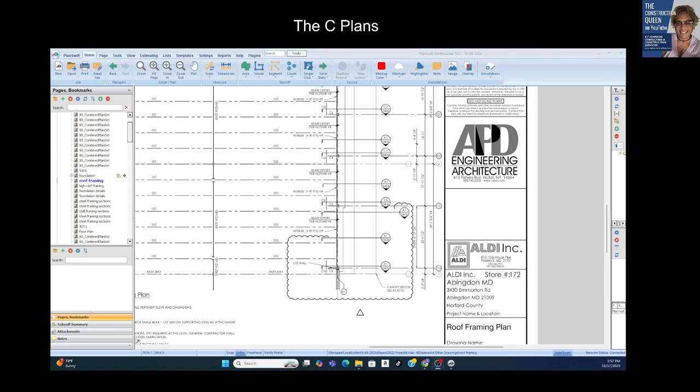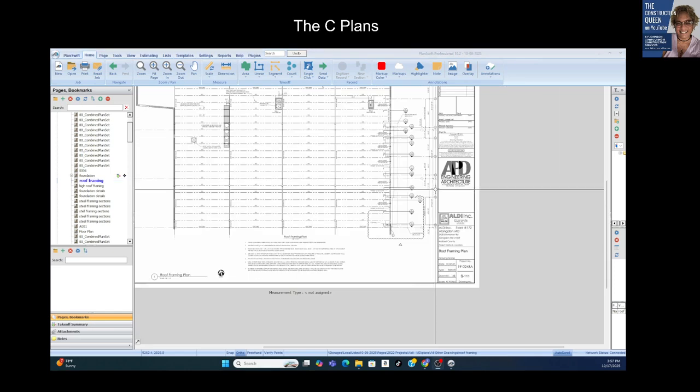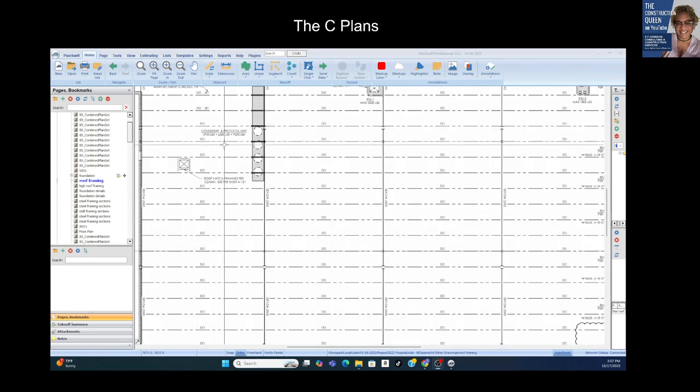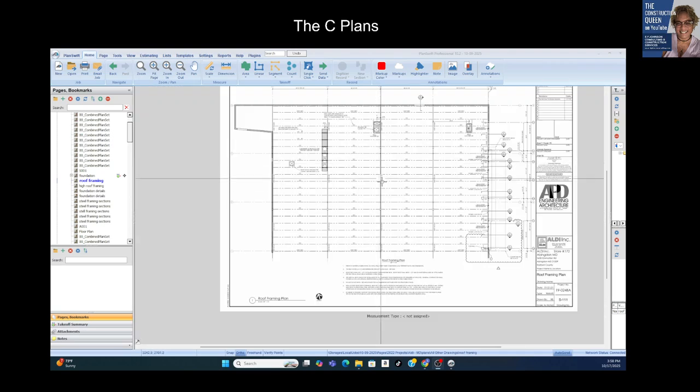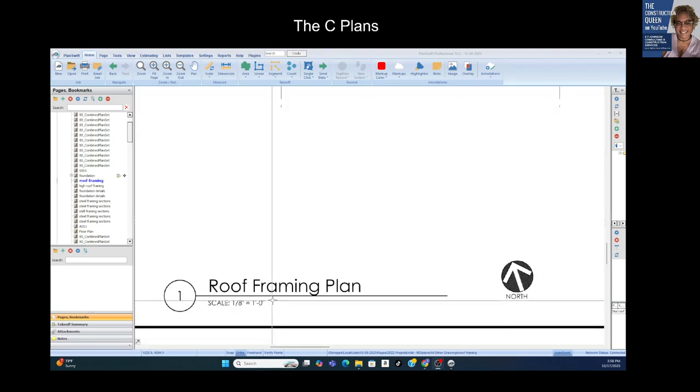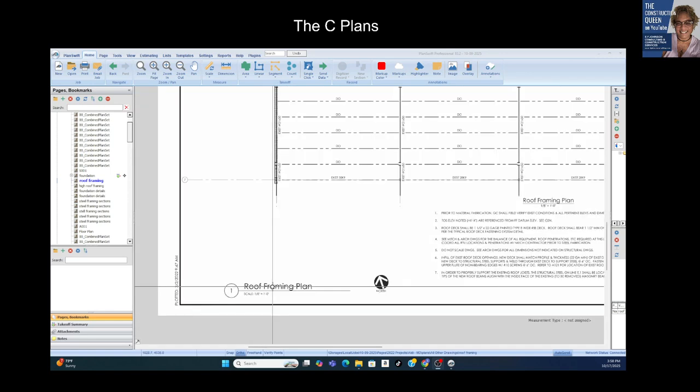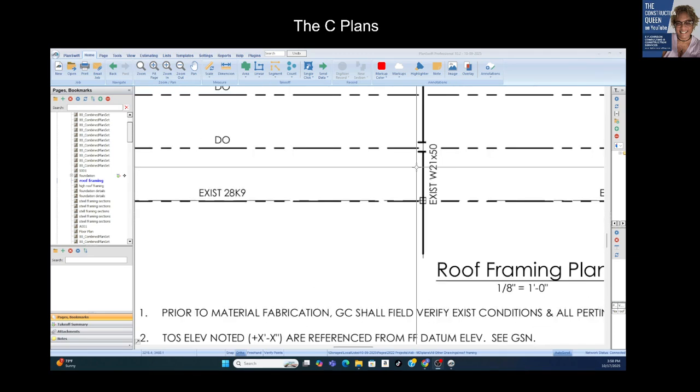All right. So now let's look at the structural framing plan and how they represent the portions of the framing. And so we know that the structural framing always begins at the roof if there is any. And how they represent it really depends on the type of member.